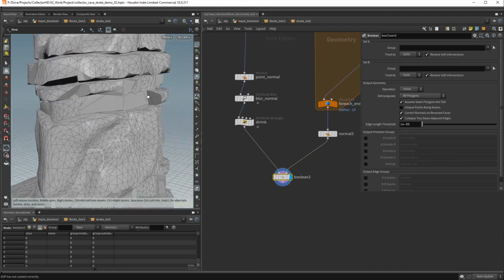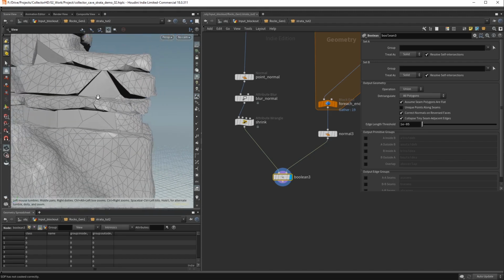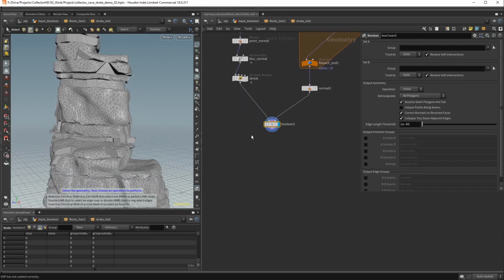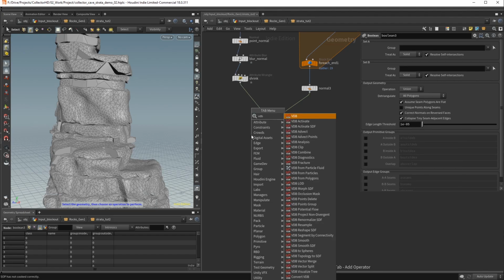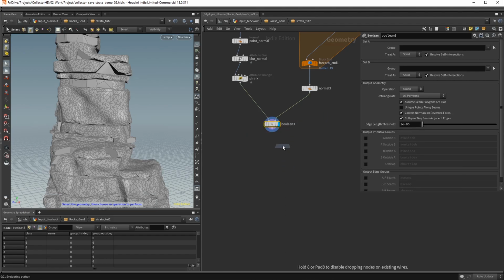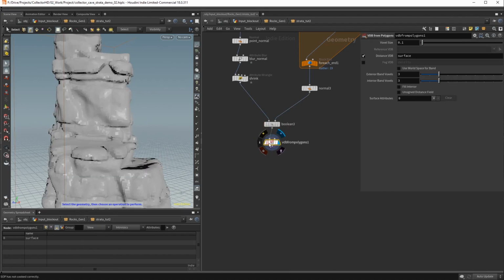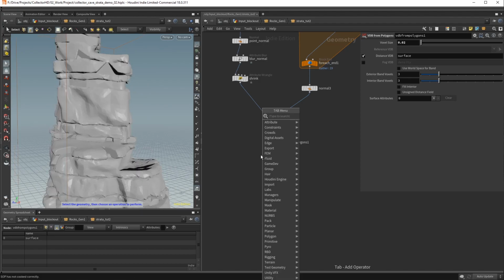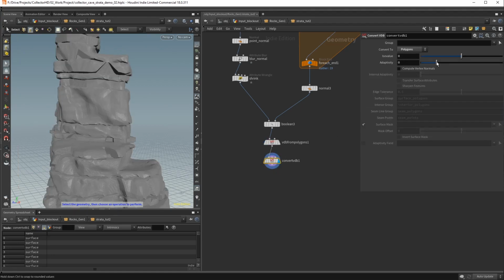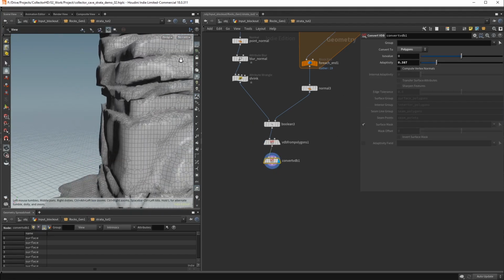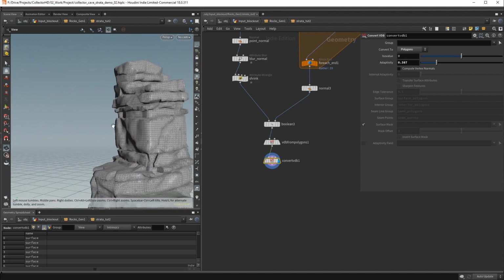And the last thing you can always do is just do a quick conversion back and forth to the VDB. This will just kind of heal all the self-intersecting parts or any weirdnesses in your geometry. Just a nice thing to do. Just set a small voxel size to not lose any details. Then convert back to polygons, and then you can add a polygon reduce node to restore a reasonable polygon count.